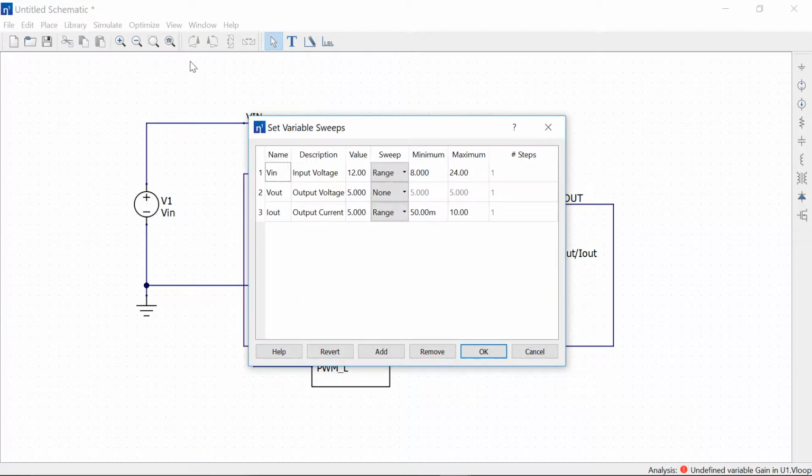We'll choose Edit Design Variables from the Simulate menu, and then add 2 new variables. The first one, called gain, is our DC gain with a typical value of 30K. We'll set a logarithmic range from 10K to 1 meg. Now we'll specify FZ, the zero frequency, and set that to 30K as well. We'll have it range logarithmically from 10K to 100K.